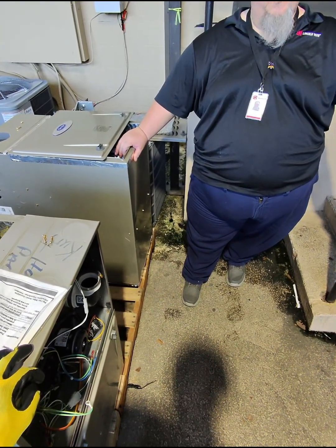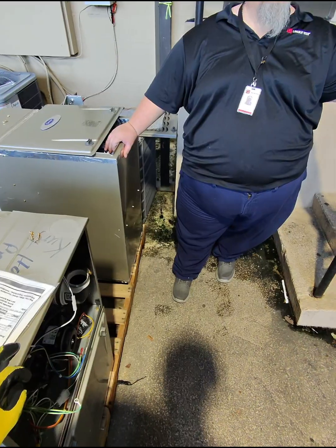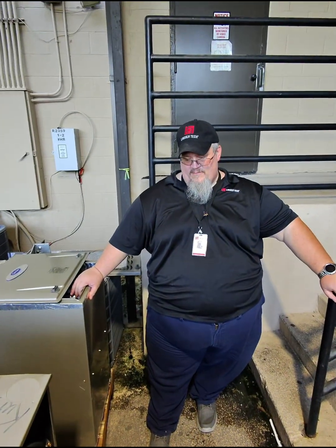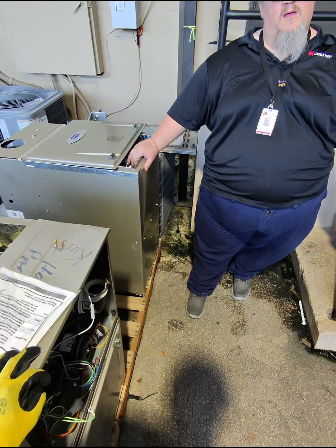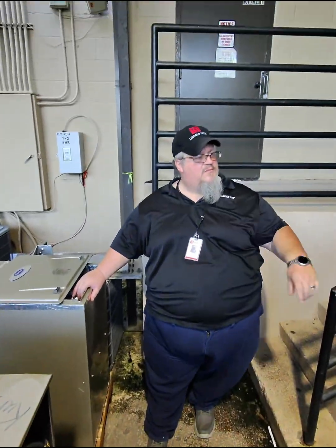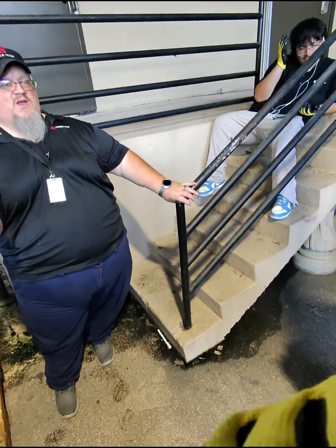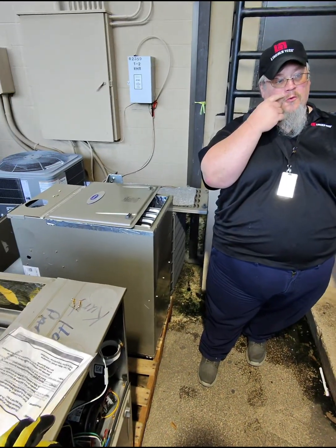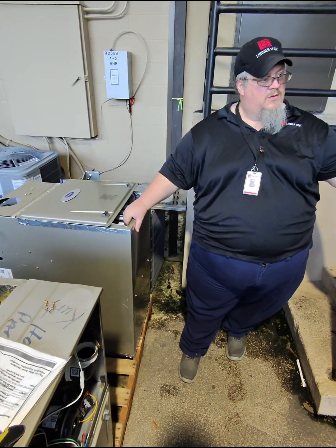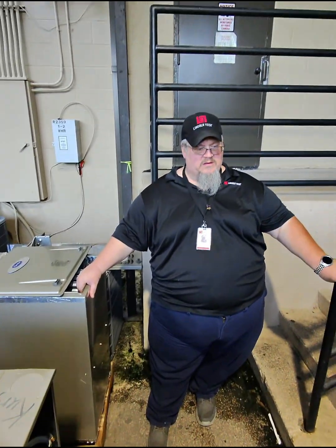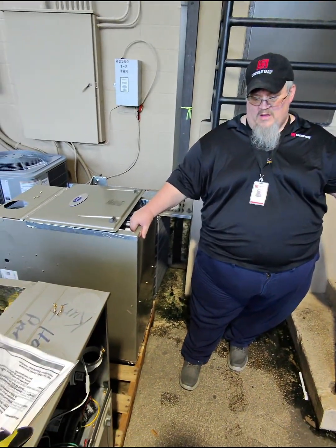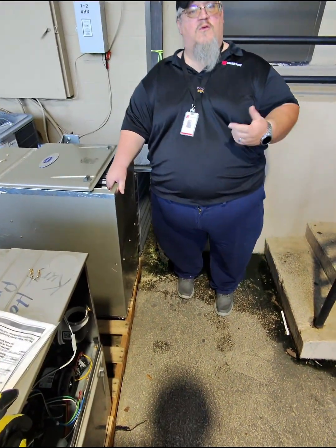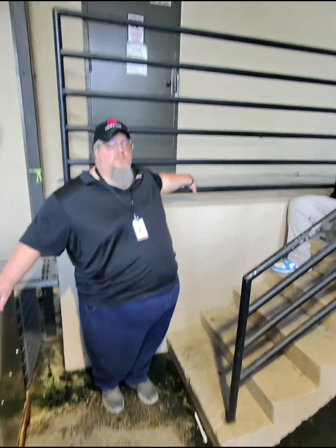Well, you gotta inspect it, but how do you inspect it? Gotta take this thing apart. You gotta take the blower out on the bottom, and then look up. You'll see the bottom side is the entering side of that coil. It does have an airflow arrow on it, but that's where it's going to be dirty, right there at the discharge of that blower.